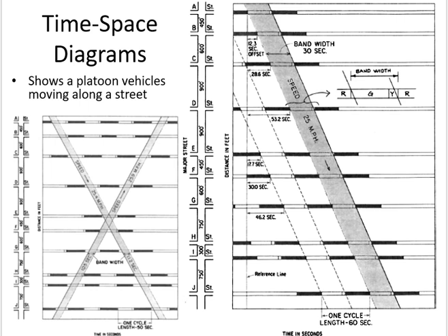The rule is, these timings are called offsets, the time which you are calculating for the green time. Whenever the value of the offset goes more than the cycle length, you subtract the cycle length and just put the remaining time.